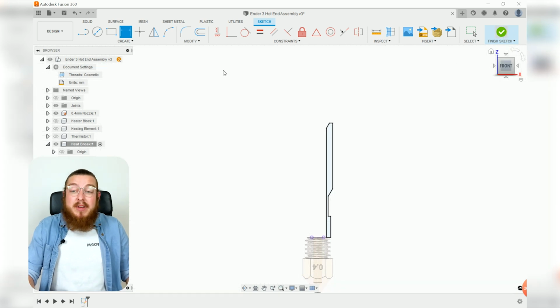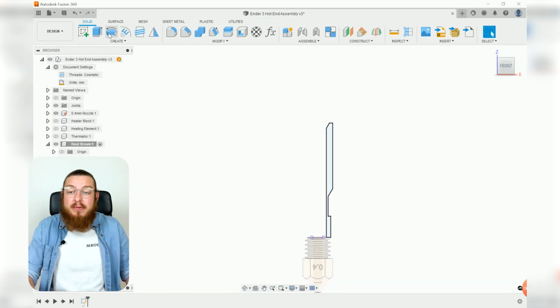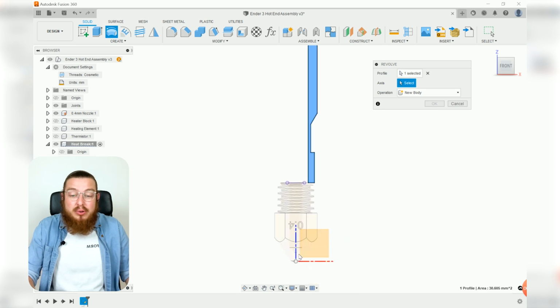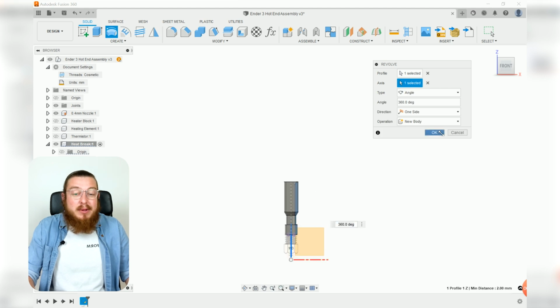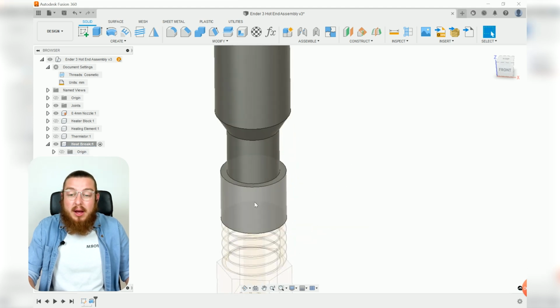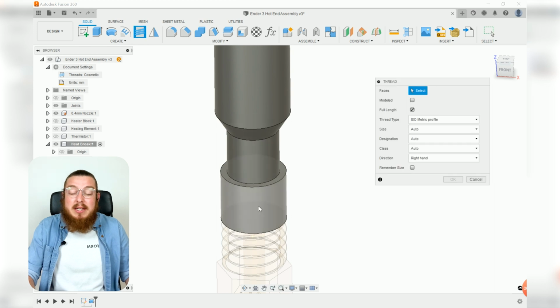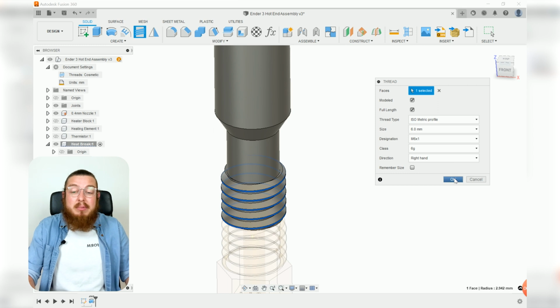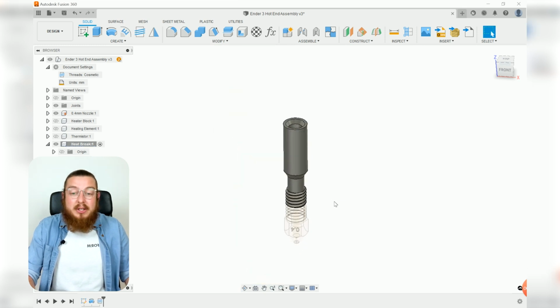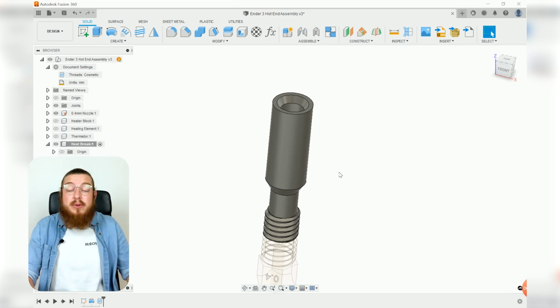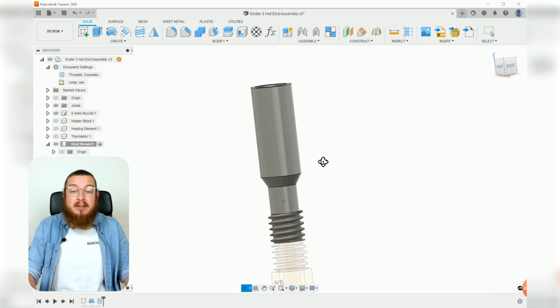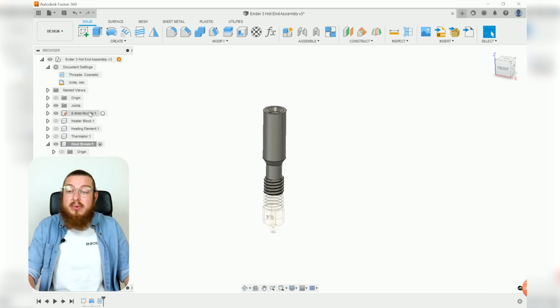So let's go ahead and finish this sketch, and this is going to be a revolved profile about that blue Z-axis. There we go. And we can just hit OK, and then this top threaded section is going to receive a very similar thread down below. This is an M6, and then we can keep this as OK. Now this component is still made out of steel, and the default material for any Fusion 360 part is always steel. So we can just say this component is totally done,